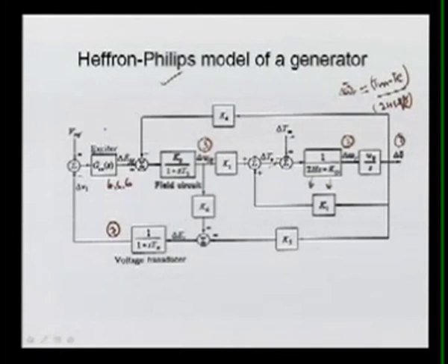Here the exciter which is represented here directly, it is having itself the IEEE type 1 DC exciter, and that has the 3 states, and that we have represented in our formulation. I will see later that it is now for one machine. Here we are going to have the 7 states. So if your number of machines are Ng, then total number of states will be Ng multiplied by 7. So these will be the states of the total number of machines.